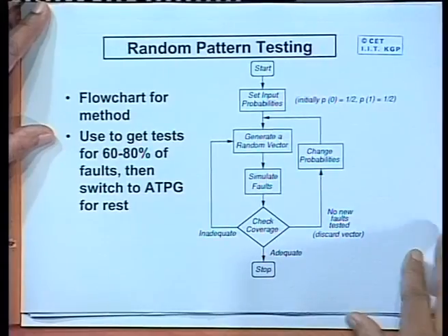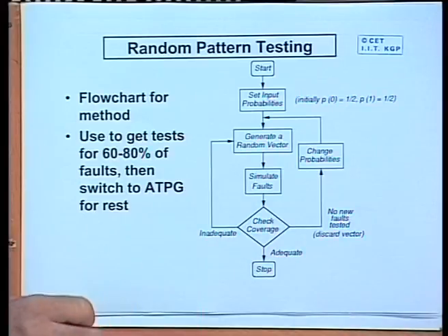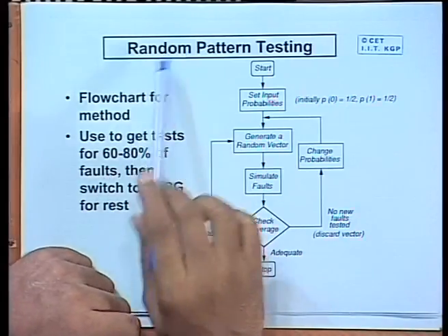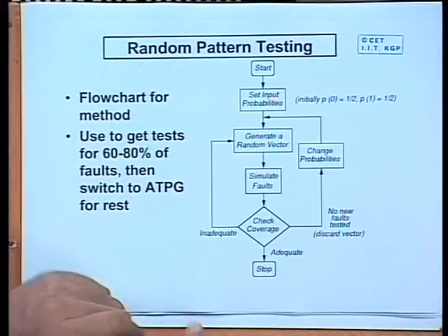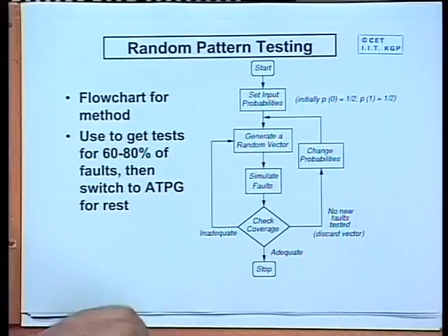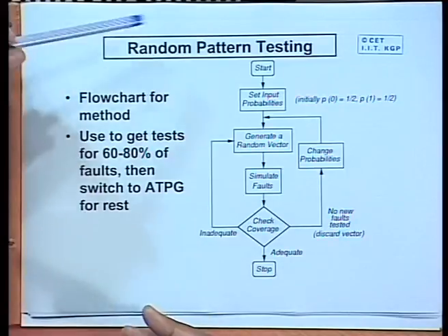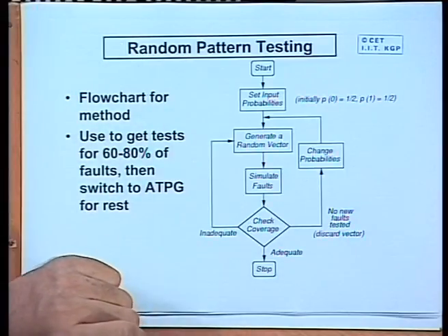Well, I am stating one alternative here, but exactly how this is done, this we will be discussing later. This alternative is something called random pattern testing. Well, actually it is not purely random, you should call it pseudo random, because these patterns are generated using some algorithm and the same pattern can be repeated. That is why it is not truly random, it is pseudo random.